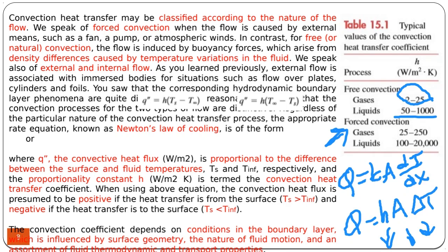In this case, the fluid will apply a buoyancy force, right? The buoyancy force, if the submerged volume is V, is gamma times V. Gamma is the fluid specific weight.